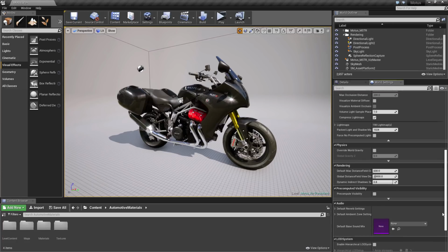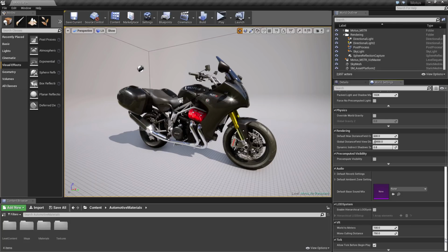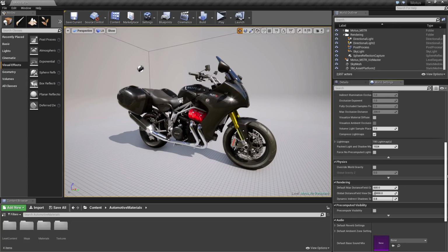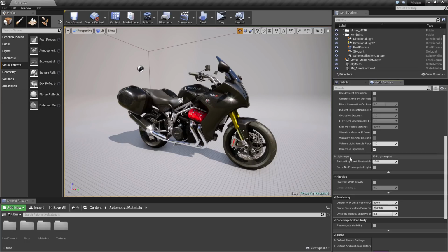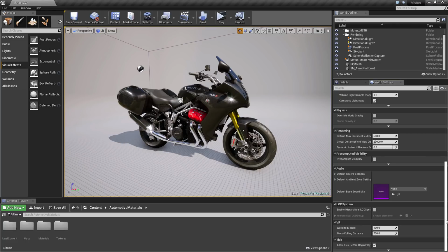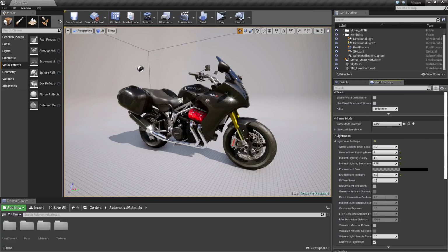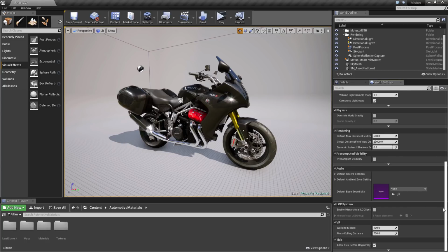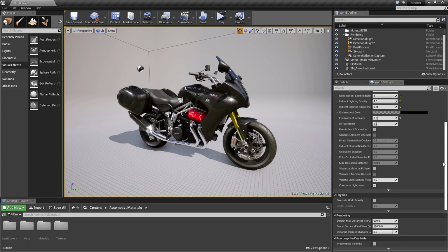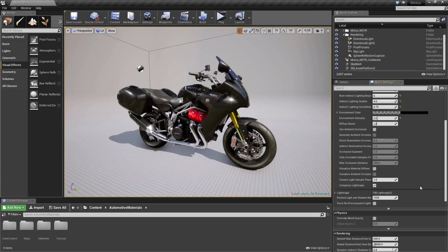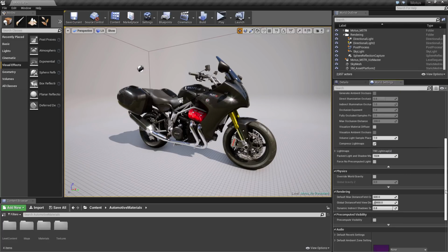Let's take a look at what happens with lights when they're baked out in Unreal and what we do with those lights or those images that are baked out. This is where we create something that is referred to as light maps. So light maps can be found through the world settings. If we go underneath our lighting setting and expand our menu out, we'll see light maps. And we can see that in this scene, I have 198 light maps that I'm actually working with.